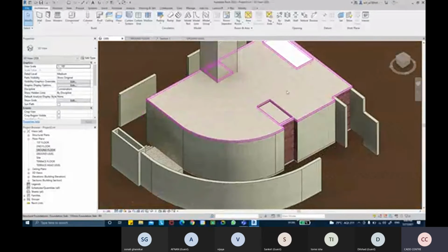Simple. So first, at least make the structure ready, and then you can start adding the finishes to the structure. So don't worry about the finishes of the walls or anything like that. First, make at least your structure work ready. If you want to create all the walls and the slabs first with the sunk slab and everything, you can do that, and then go ahead with the floorings and then the finish walls and then the railings and the curtain walls and other things.